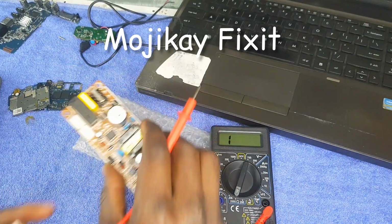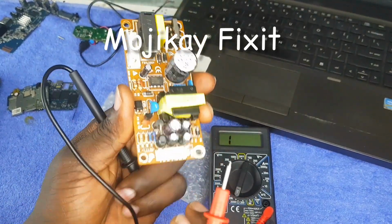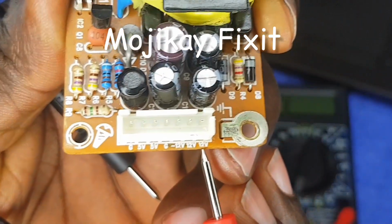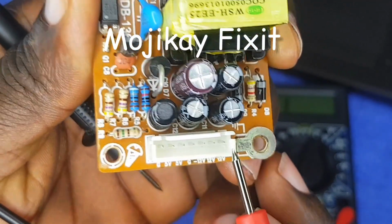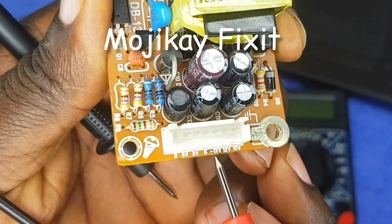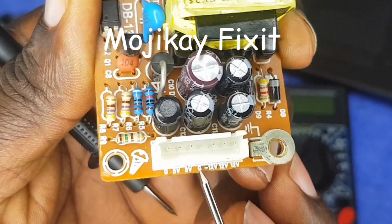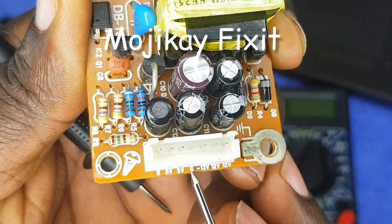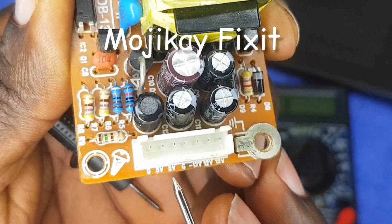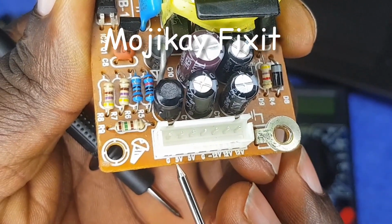Okay, and I also said that resistors are used to divide voltage. Take a look at this PCB. On this side you can see we have 12 volts, which is this pin here, and also 12 volts, which is this second pin here, and this one is 12 volts, which is this third pin here. The next pin is G, which means ground, and this next pin right here is 5 volts. You see 5V, that's 5 volts, 5 volts and ground.